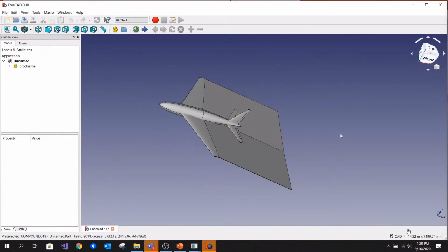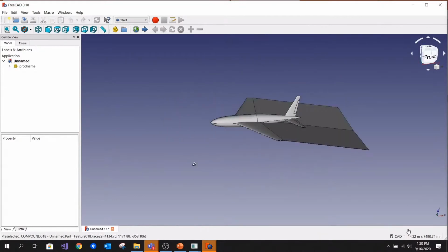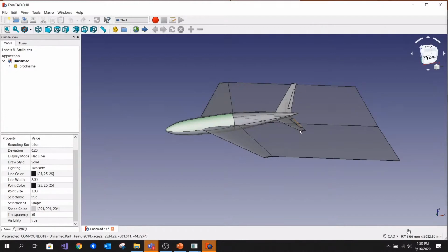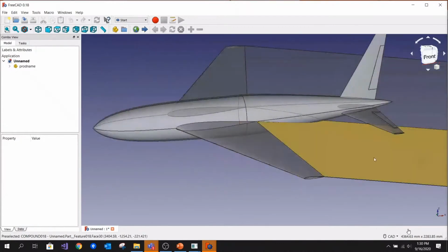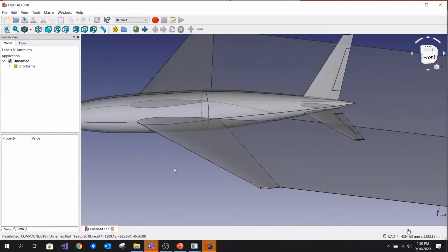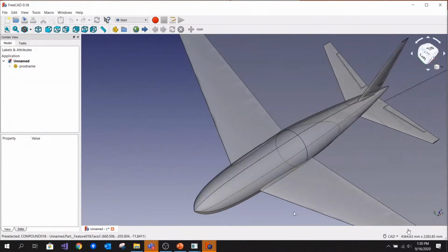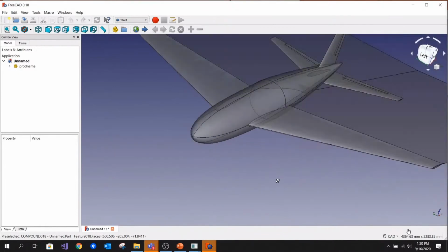And there you can see the wakes were exported. Let me try to turn on the visualization transparency. I'll do 50%. So you can see this is going to be, other than the wake, of course, a watertight single volume with the intersection curve between each component used to trim those components. So the internal part of the wing has been removed.